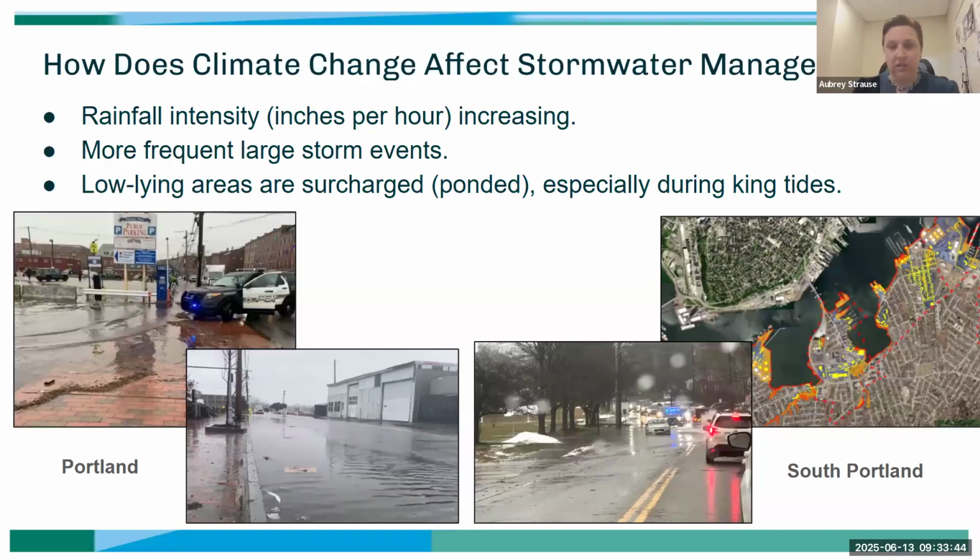Well, when we look at the charts and the tables that show us how to design these systems, what we see is county by county, we're seeing 100-year storm rainfall events. How much rain comes down in a 24-hour period? We're seeing way more 100-year storms. For those of you who have been in Maine a long time, if you recall, I think it was 2004 and 2005, we had the Mother's Day storm and the Patriots' Day storm back to back in 2 years. They were both 100-year storms, and they occurred in 2 adjacent years.